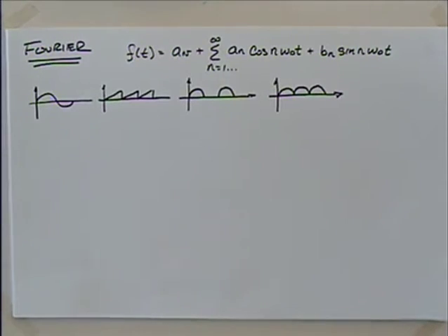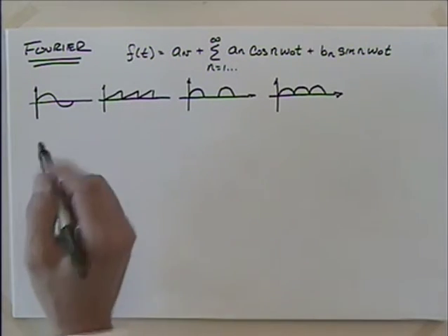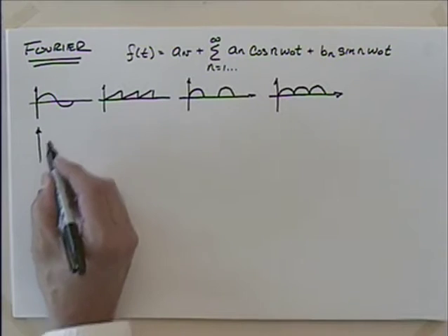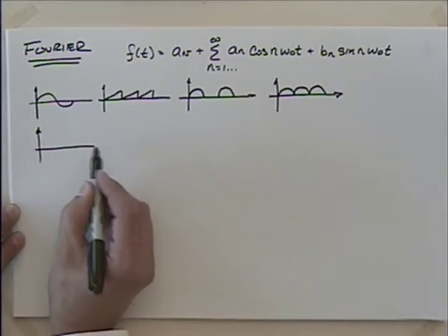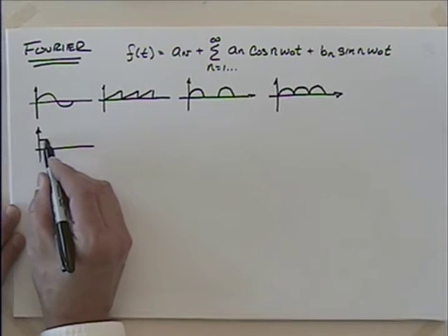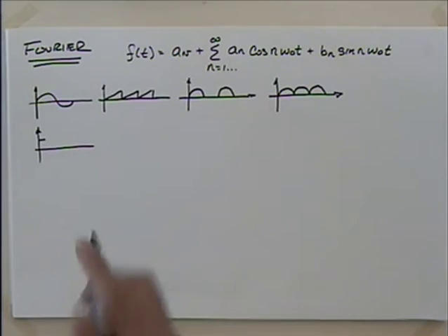We'll talk about taking that and trying to clean it up and turn it into a DC. Some people talk about duty cycle or pulse width modulation, fairly common now in a lot of things. Let's say we want to take a DC signal and have some variable speeds. Like in your car, you want to control the fan speed on the heater, or maybe dim the lights in the dash.